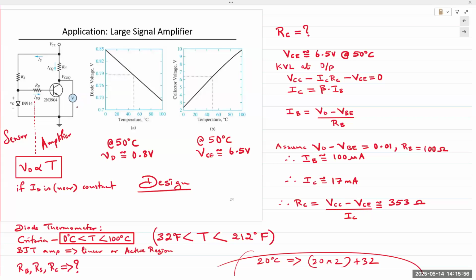So the output of a sensor, whether it's diode based or any other kind of sensor, would be small, either a smaller voltage or very small current. So before we apply this sensor output to our instrumentation systems, we need a way to convert the electrical signal and translate it into a readable display. We want to convert it into degrees Celsius, degrees Fahrenheit, which is what we have here on the wall. So in order to do that, we use a BJT. That small signal coming from the diode is now amplified.